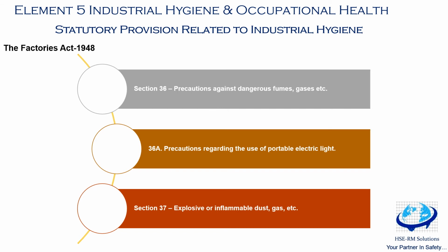And the second point is, no person shall be required or allowed to enter any confined space as is referred to in subsection 1 until all practicable measures have been taken to remove any gas, fume, vapor or dust which may be present so as to bring its level within the permissible limits and to prevent any ingress of such gas, fumes, vapor and dust, and unless a certificate in writing has been given by a competent person, based on a test carried out by himself, that the space is reasonably free from dangerous gases, fumes, vapors and dust.